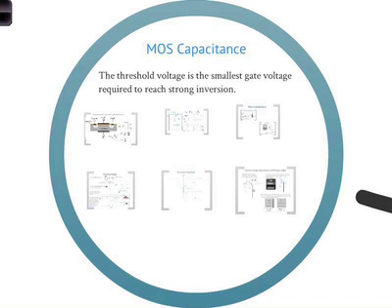In the case of the P channel, until I reach Vt, I expect zero current, so there's no channel. Right? So I expect nothing to happen until I hit here, and then something happens. This is, of course, a linear region. We'll talk about that. So that's the idea of the Vt. You need this much voltage to create strong inversion and account for the charges in the depletion region in the substrate. Okay? So that's the physical meaning of the threshold voltage.